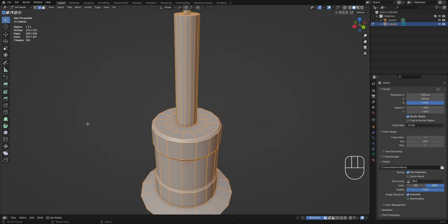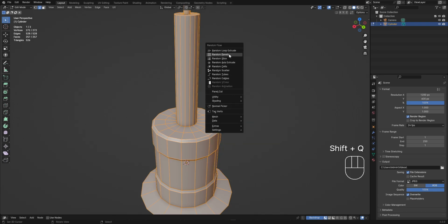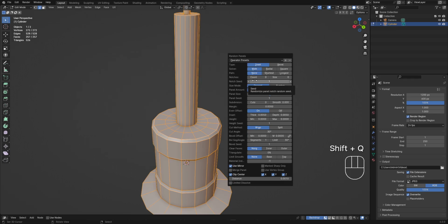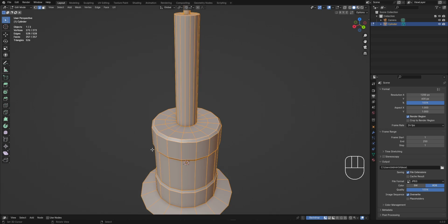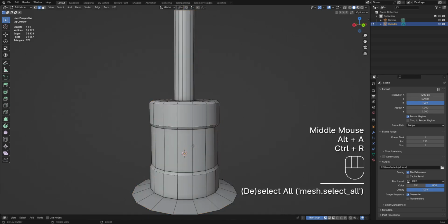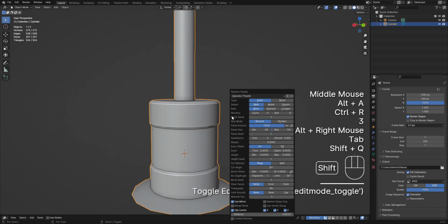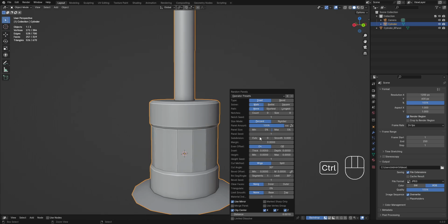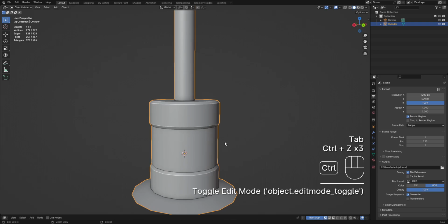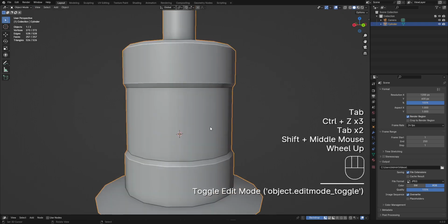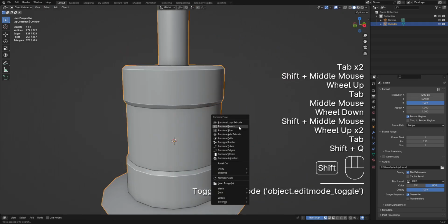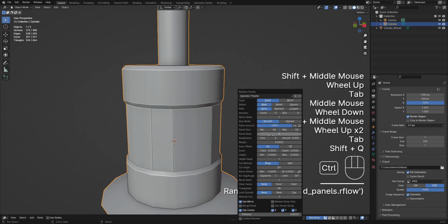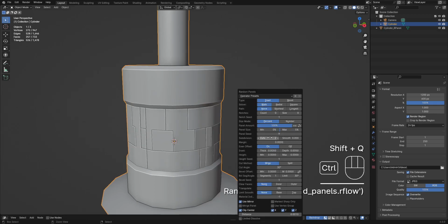And when you increase the subdivision, it means that the randomizer will have more faces to play with, and therefore generate more detail instead of just using 0. So when using 0 subdivision in this case, there's not a lot of faces going on, and the randomizer cannot, of course, create patterns. You need to increase the resolution.